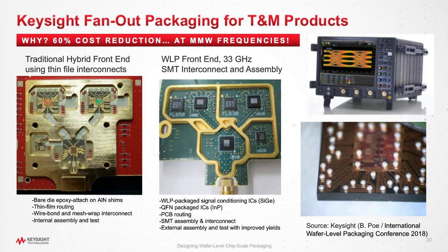And the one area of cost that I think probably sticks out to you is the shielding. If you look at the left-hand side package, there's a big hunk of metal on there, and of course there's less metal on the right-hand side. That speaks to one of the advantages when you're able to contain all of your traces, your interconnect and circuits, into a smaller package. That means the signal is not going to radiate out as much, especially at higher frequencies. I showed you earlier some of the antenna sizes: when you get up into the gigahertz, they start to become on the order of the package.